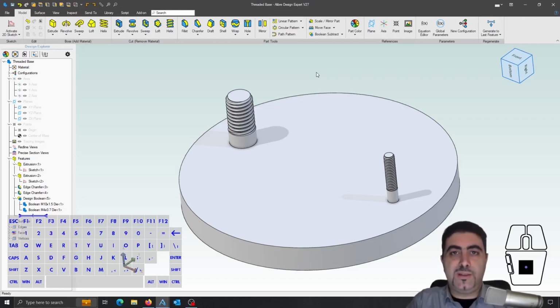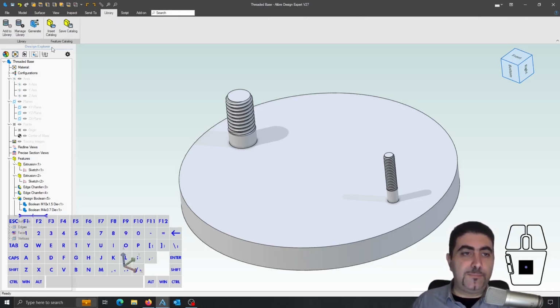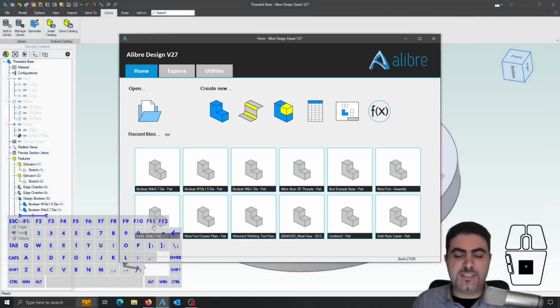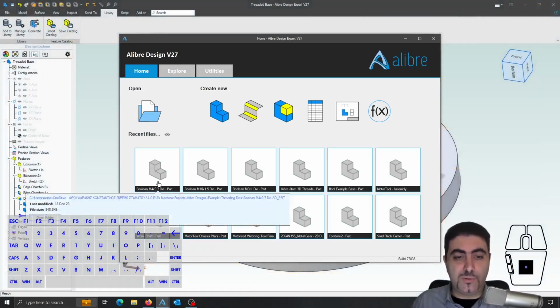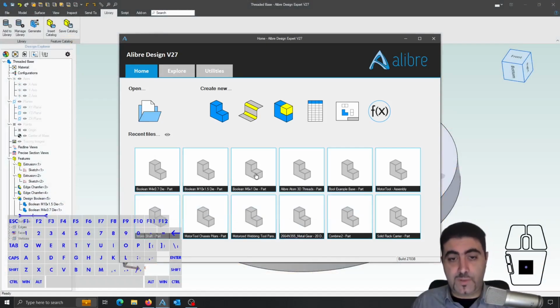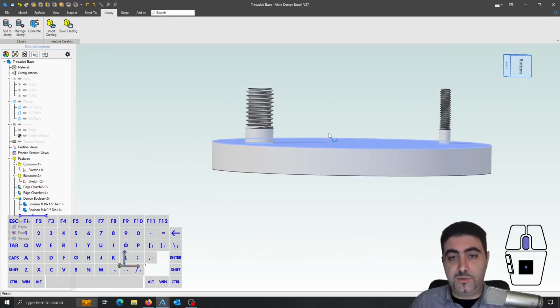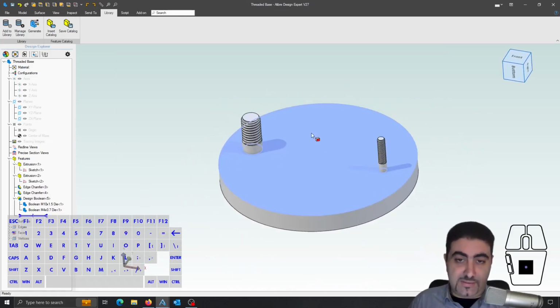So you see that the way to do it in Alibre Design Professional is very, very similar to how you would do it in Expert, right? You might not have the generatability, right? So it will take slightly more time because you need to open up one of the dies you already have, insert the new parameters, and save as.